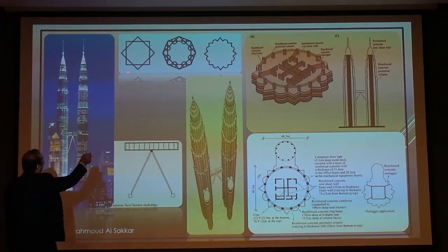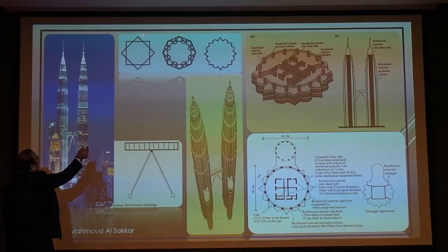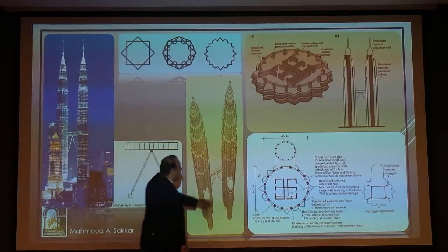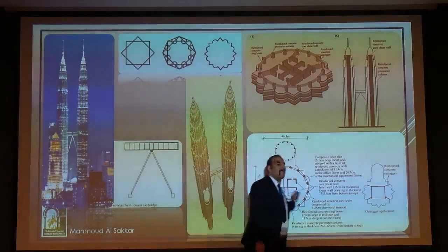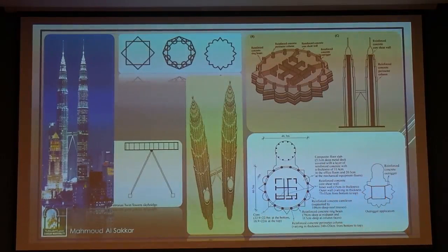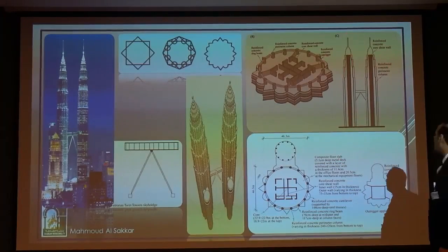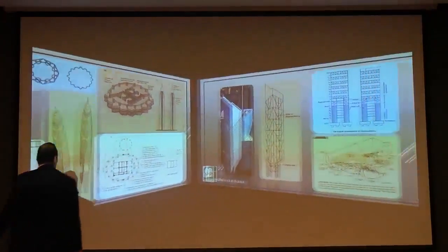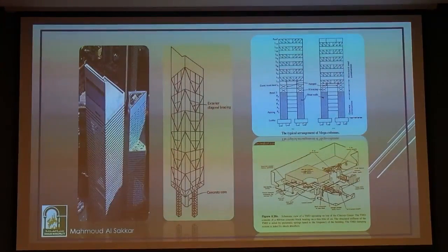Each tower is actually shaped like an Islamic star, and to make full use of the area, they made some curves, came up with a shape, and then designed the structure system. It's columns spaced 9 meters apart, but the columns are huge. It's a mega column. If you increase the distance, you increase the size of the column. So that's the Petronas Tower, the most famous towers in Malaysia, from the time of Mahathir Mohamad, and it's a tubular structure.